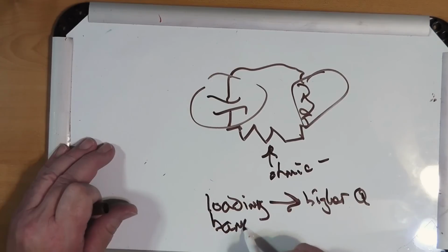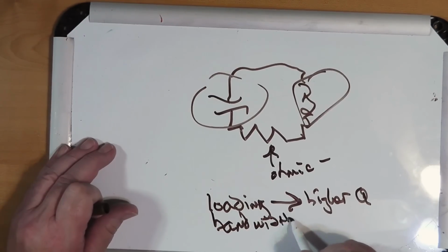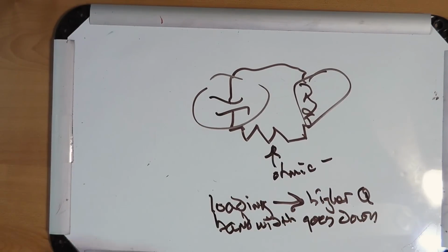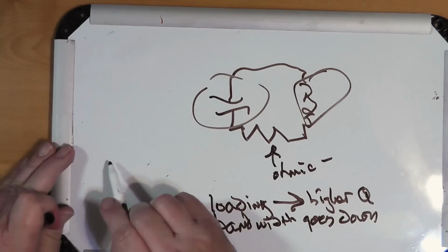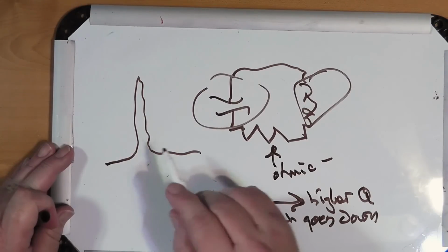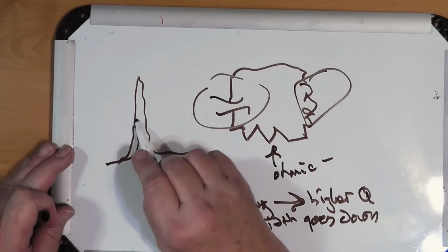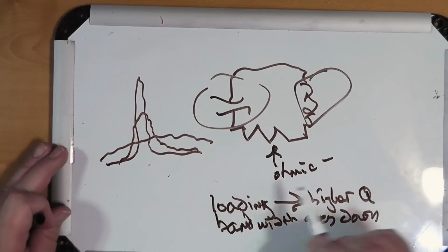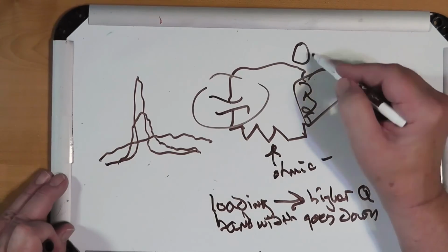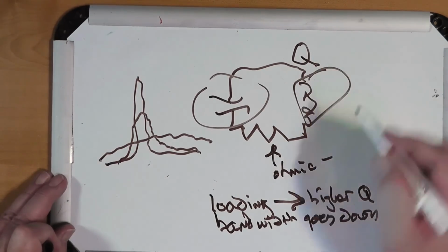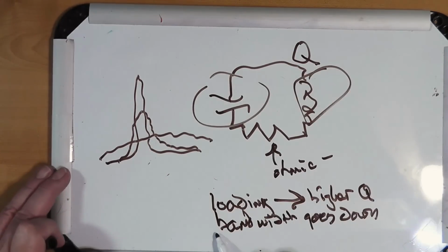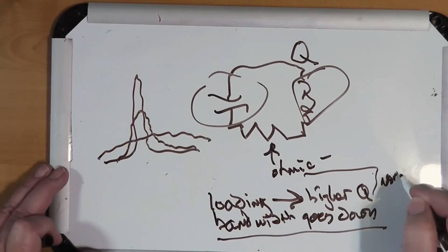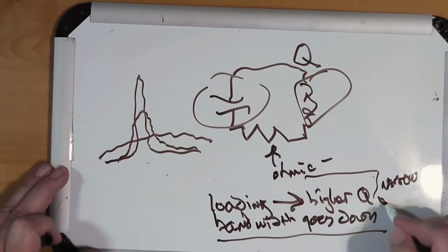As the resistance goes up, the bandwidth of this circuit goes up. So instead of a real sharp point, you'll get a point that's like this. And if resistance keeps going up, you end up with something like this. It's pretty broad band. Okay, but notice the Q, the transformation factor, goes down as the bandwidth gets wider. So if you do an 80 meter hamstick, what you get is something that's very high Q.